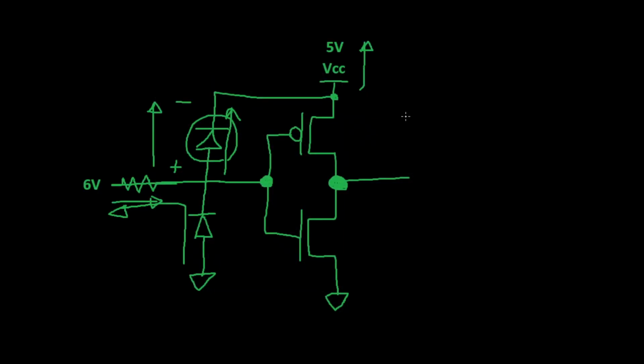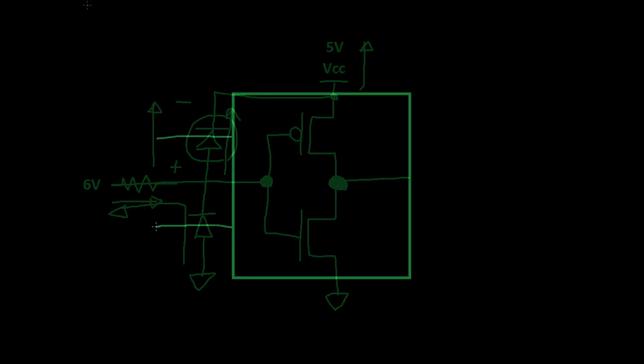In other words, if the inputs to your logic device are running directly to a port that goes outside of your system, and humans will be able to interact with this port, then you definitely want to add some level of ESD protection external to the device. I'm not going to go into extreme detail on ESD protection here. It's just important to know that logic devices aren't good enough to provide the system level ESD protection that you need.